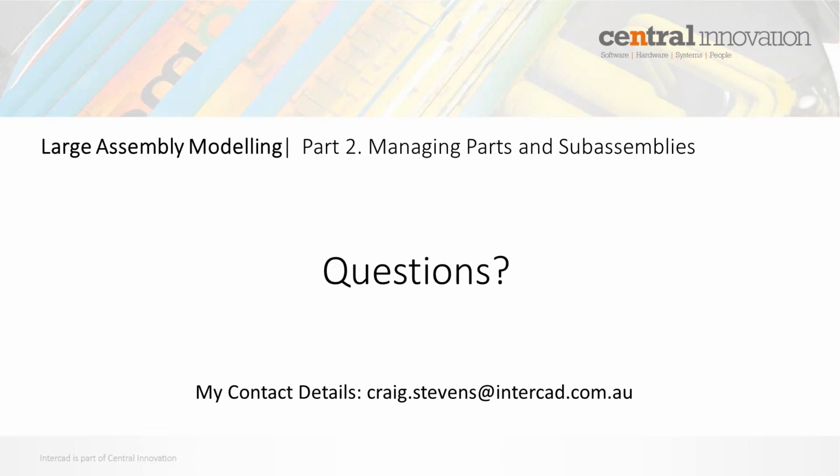Fraser, can a drawing be set up to default to high quality? No, and I think one of the things that I was going to mention, if I didn't, is that shaded views at the very least come in as draft quality by default. If you want them to be high quality, they actually need to be changed manually on the drawing sheet. Other views, your regular orthographic views, as long as they're not shaded, if they can come in as high quality, they will.